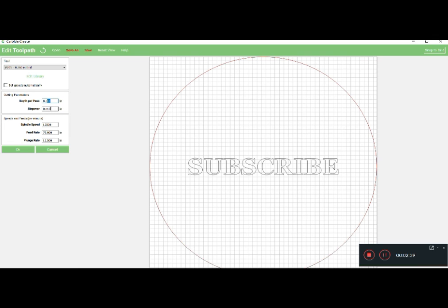The step over is basically if you were doing a pocket, okay? If you were doing a pocket cut, that bit will go around and around and around. If I put step over at a very small rate, say I had a 1/4 inch bit but put 1.3, well, if I were to put a 1/4 inch there, it would take one out and move over and then over and over. It's too much. So you want to go about half the width of your bit so you can make a nice, clean, smooth cutout. So step over, I'm not very concerned with that because we're just cutting out this circle here. I'll show you the step over in a bit when we're actually cutting out the letters.